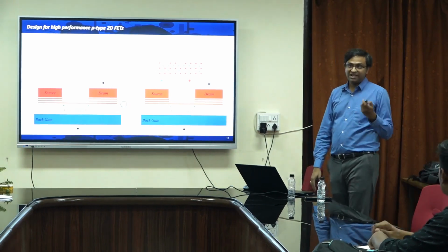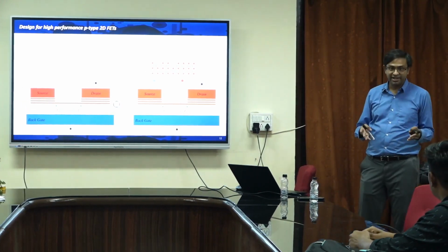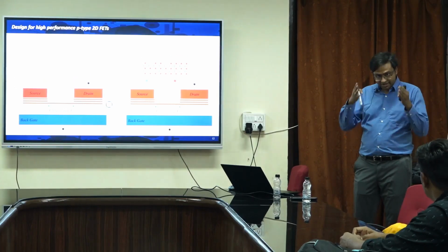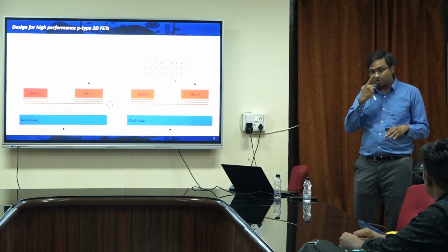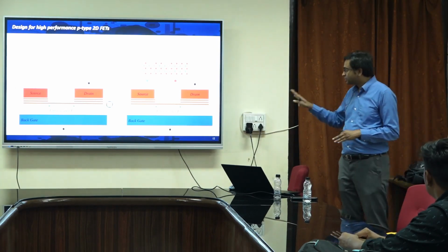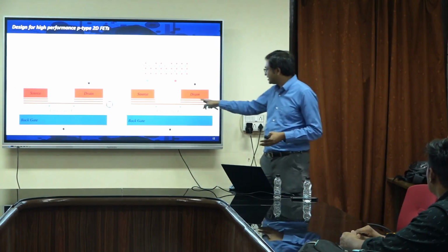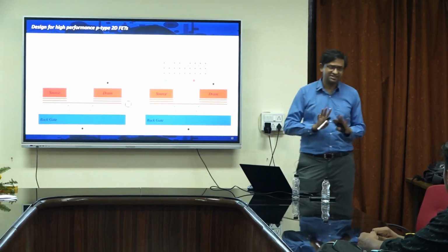That is why plasma etching is always good. This is reactive ion etching, very directed, very anisotropic, right? If you do wet chemical etching, that is more isotropic in nature, right? So plasma is good. Of course, there is some penetration in this direction, but that is actually minuscule.